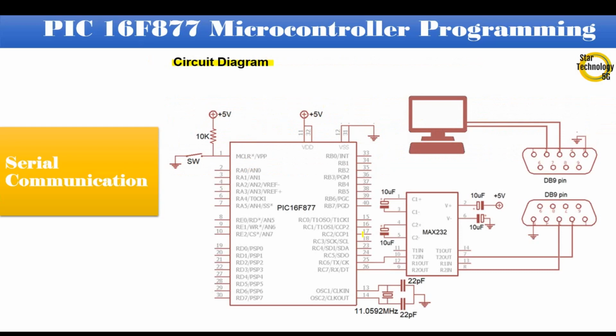Here is the circuit diagram we are using in our project. It is a PIC16F877 microcontroller. Pin number 1 is master reset. If we press the switch it will reset the microcontroller. Pin RC6 and pin RC7 are interfaced with MAX232. Here are the capacitors interfaced with MAX232. The value of the capacitor is 10 uF. An output of MAX232 is interfaced with the DB9 pin connector and the other side of the DB9 is interfaced with the PC.